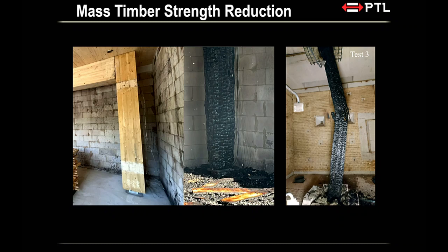So what we have here is a compartment with a glulam column, glulam beam, and a CLT floor, all right? They did this compartment fire experiment, and at the end, what they found is the column is a bit tapered, right? A little bit short, a little bit skinny, slender at the bottom. And you might wonder, why does this happen? I thought the compartment is all uniform, like your single room involvement, everything is 900 degrees Celsius. Well, not quite, okay?